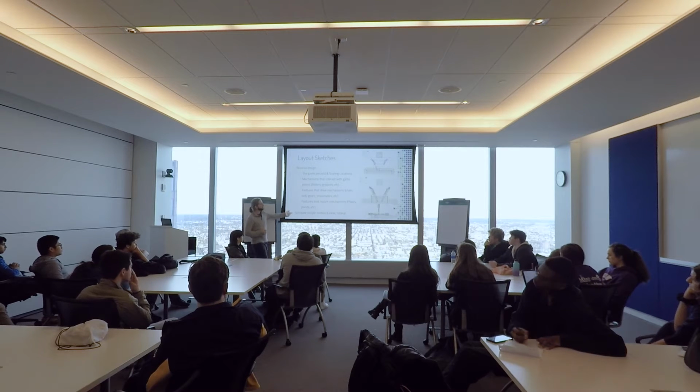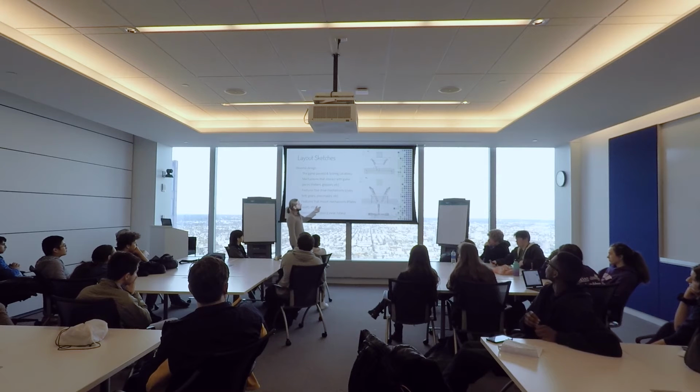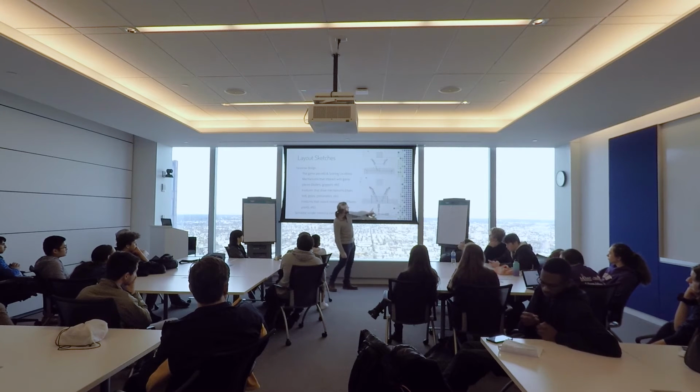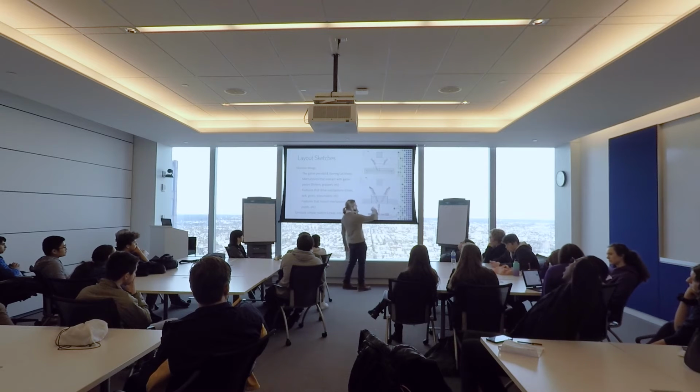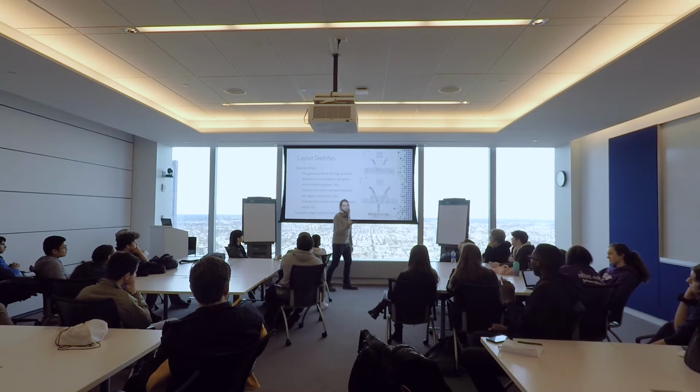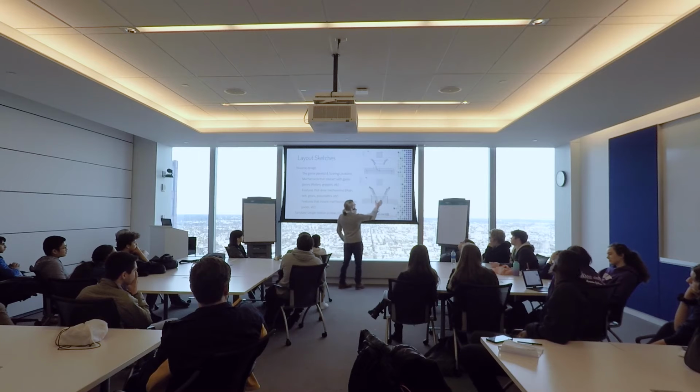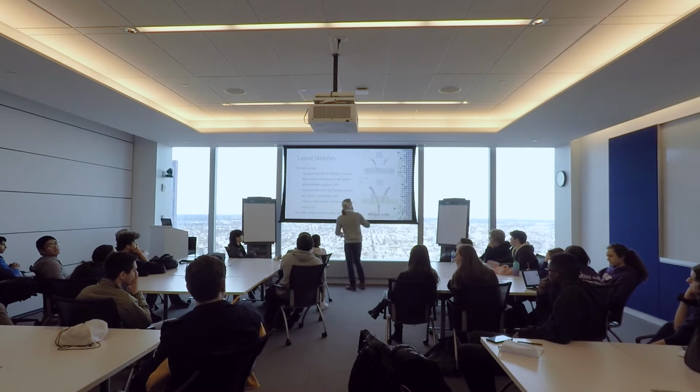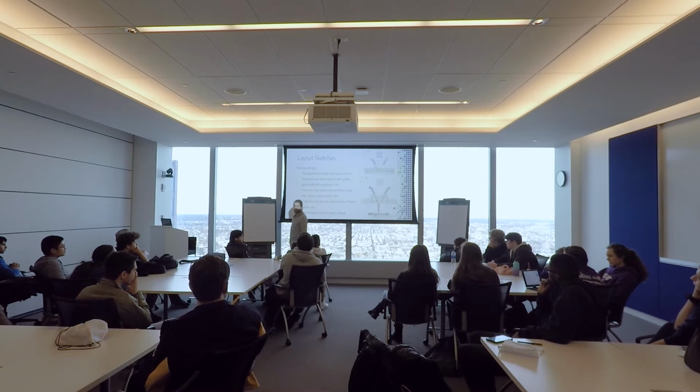In these layout sketches too, you can simulate motion. In this sketch, I forget where I had it driven, but I had a dimension that it could convert from a driven dimension to a non-driven dimension. And you can actually open these and see how they pivot about this point right here, so that I can see how it would actually grab onto the cubes.